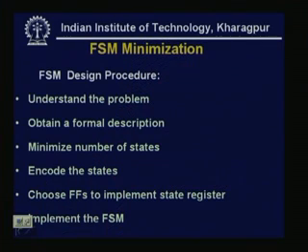We will not keep too many states, because if the number of states is more, then more flip flops will be needed. We have already seen that for n states, log n flip flops are needed. Then encode the states, which is state encoding. Then choose which flip flop we want to utilize for the particular application, and then implement the FSM.